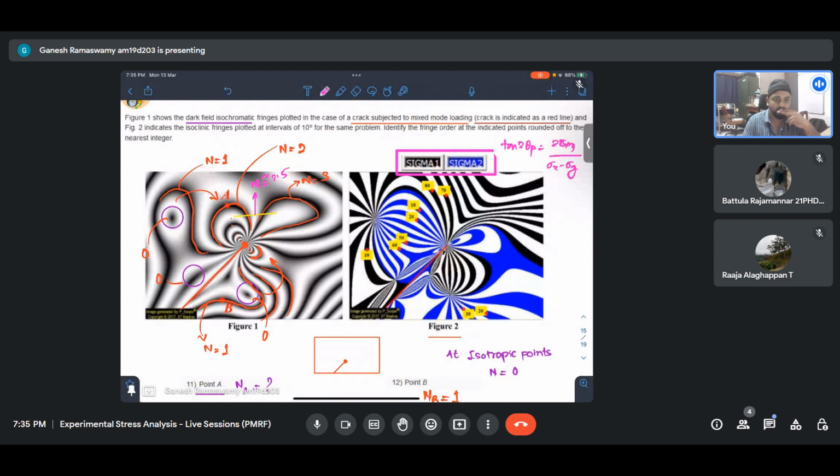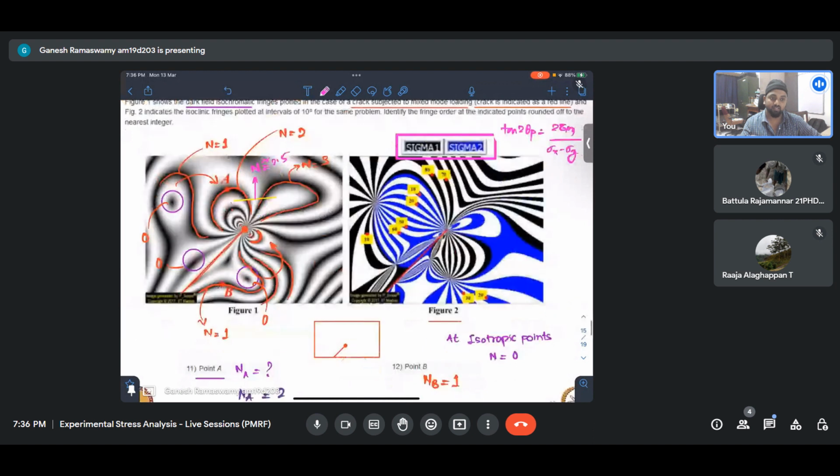So essentially, you need to do some unwrapping, because conventionally it is quite simple for a simple problem. But if you have to code it and do it digitally, then this tan inverse creates problems. The domain will be restricted, which are called wrapped isoclinics.